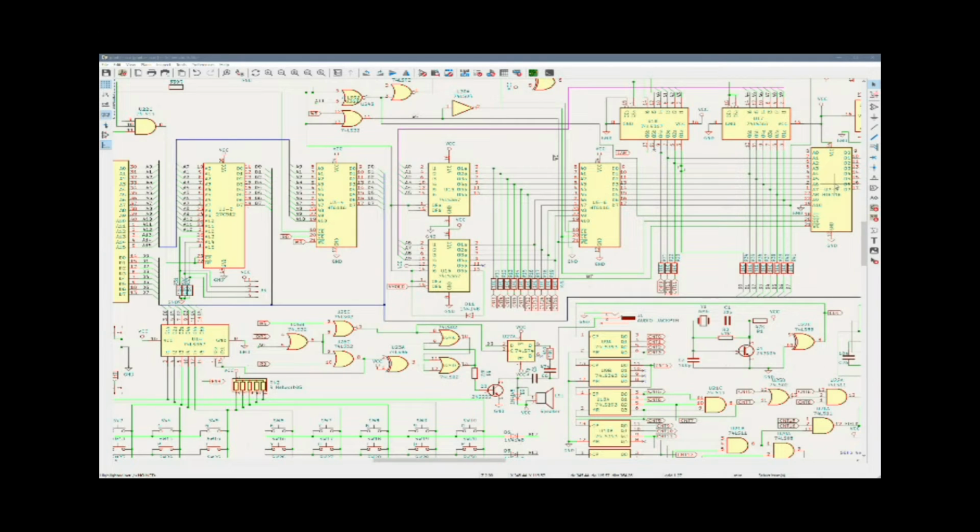Okay, I think I tracked down the problem to here. This is the character set RAM, and these are the address lines that go into it. For different cells to get corrupted, it must mean that these addresses have the wrong values on them when this write pulse comes in. If we follow this write pulse around, it comes over here to some logic that's taking the write from the CPU and merging it with the MREQ line. It's got a weird little resistor thing here, don't worry about that. But anyway, write comes from there.